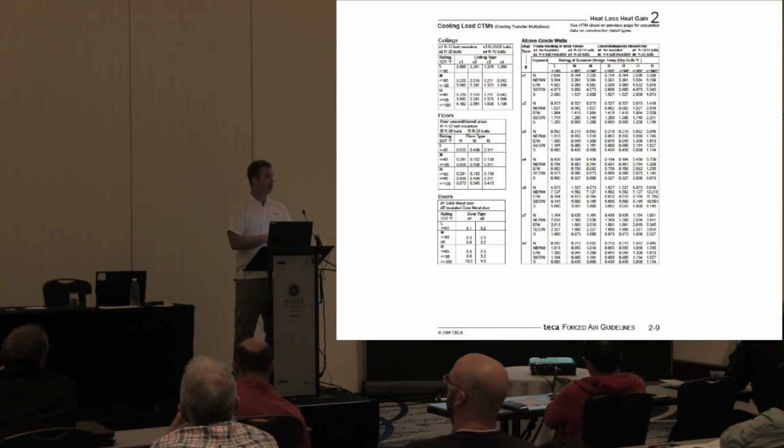But we want to make sure that temperature is set up so that the heat pump turns off and the gas runs, because the gas and the heat pump cannot run at the same time if the whole system is put in for code anyways.